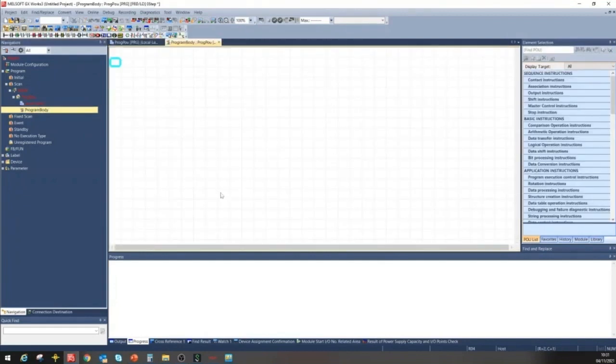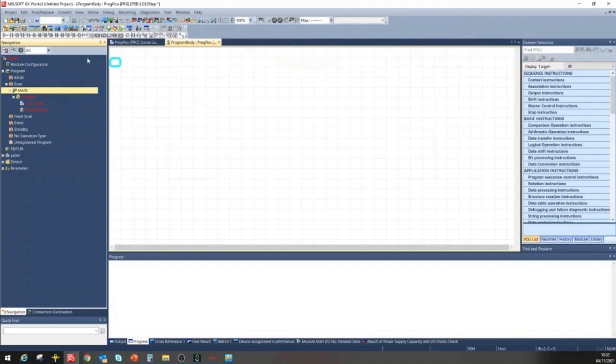So we'll come here to define local labels, in this case for this program, and a program body that is composed in this way because it is in FBD. We will see the red colored function block. Function, as we saw before, at the moment we have nothing. We could create functions and function blocks. This will also be a topic of the third part of the course.